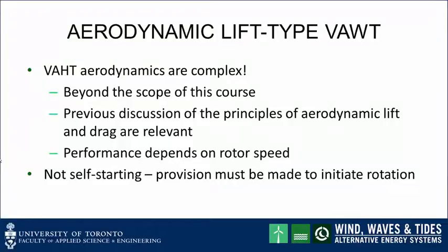So for example, electrically, you can operate just for a brief moment or two the electrical generator as a motor to turn the rotor up to some speed, and then it generates enough tip speed motion to create the proper wind vector triangle to generate substantial power, right? So that's a technicality that can be overcome, but it just exists.